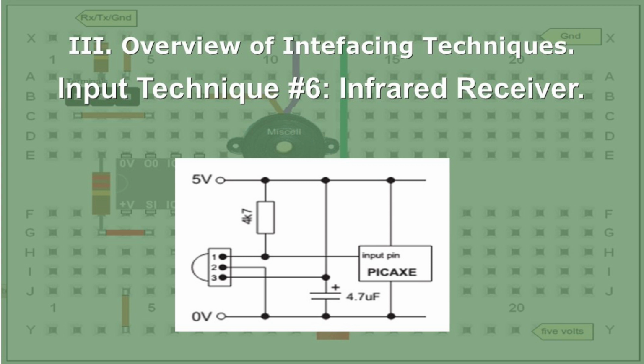And you can see there they're pulling it high with the input pin there with a 4.7K resistor. You can see it right there in line. They're pulling it high and the device goes low. Pin 2 of the IR receiver provides ground. Pin 3 provides power. And that cap in there is what Gordon mentioned in his previous hour, power supply filtering. It was amazing that the 3300 microfarad cap cleaned a lot of that radio up.